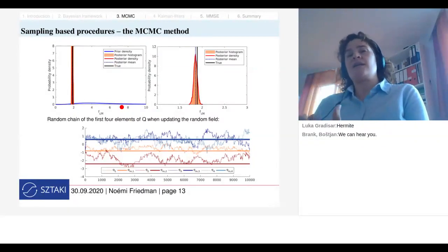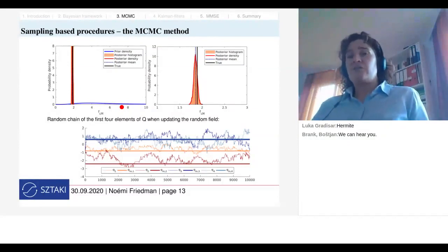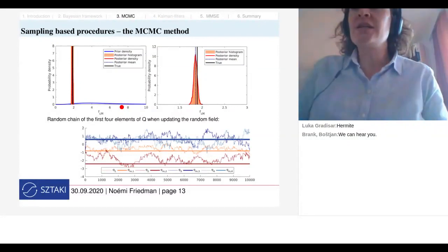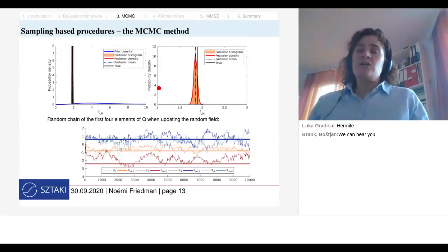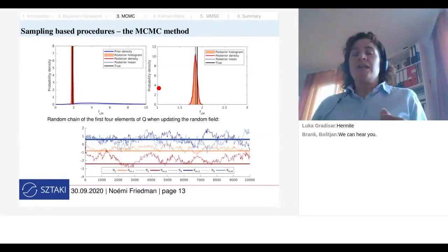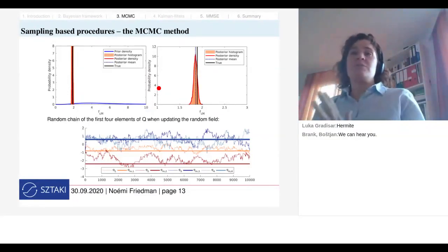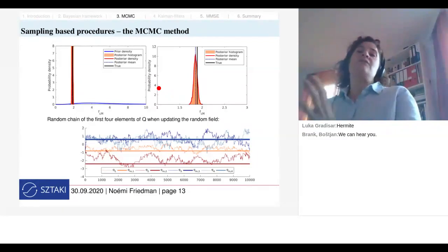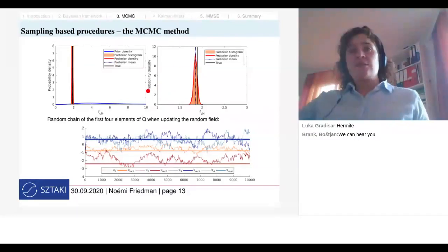How big is the variance of the measurement error? If I know that these are really, sorry for the word, shitty measurements, then you choose a big value for the variance of the noise, and then you cannot update your knowledge that much, because you learn something from the measurement, but you still trust the model more. And how the prior probability will change depends on how much you trust your measurement. If you really trust the measurement, and if it's telling you something completely different than your prior distribution, then it will really shift it, okay? So this is the way it works.